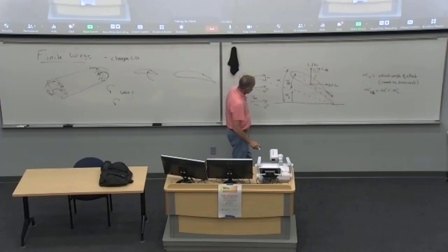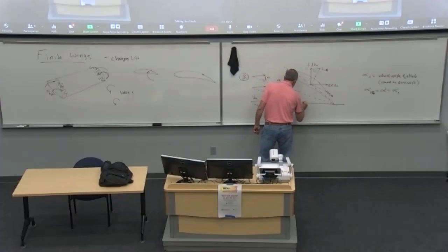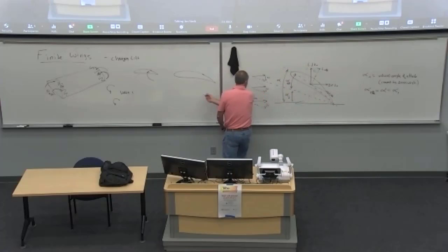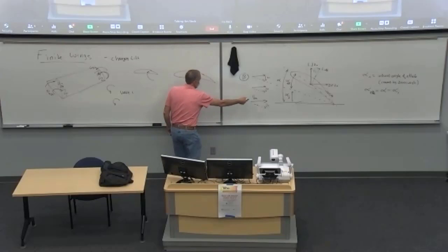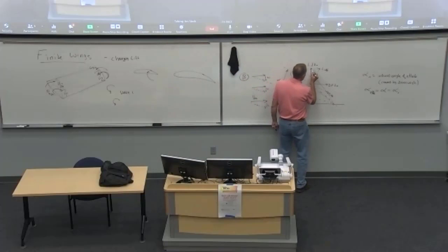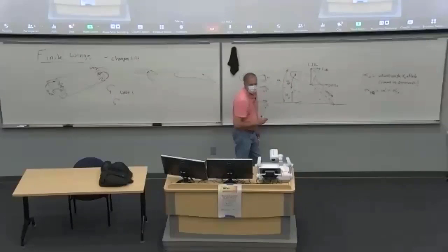And the reason that's important is that our airplane is flying along this way. But the regions of the wing that get hit by the downwash, it shifts that angle. But we're still wanting to fly this way, so lift counteracts gravity and thrust counteracts drag for the airplane. But now, with the downwash, we get a little bit of the lift vector actually acting backward. And that's induced drag.